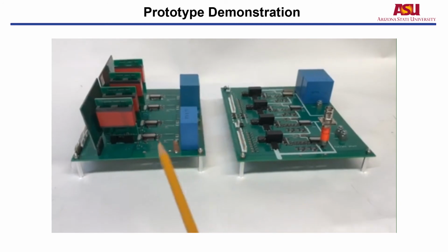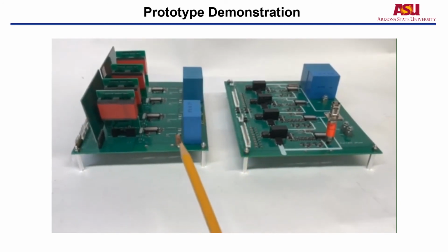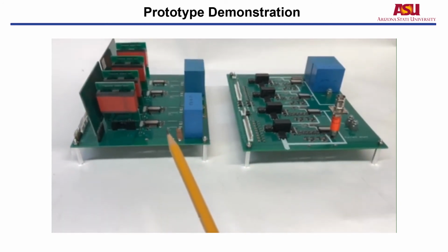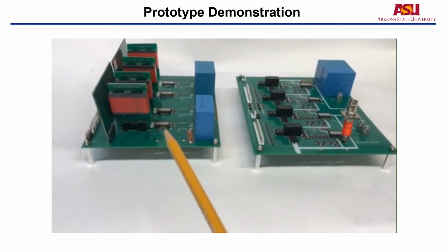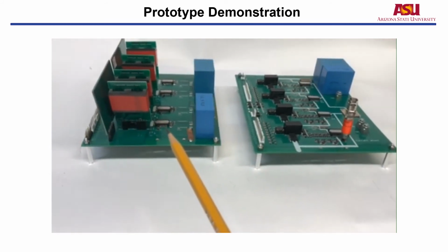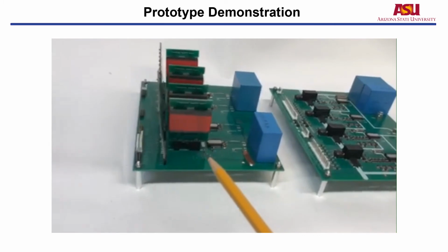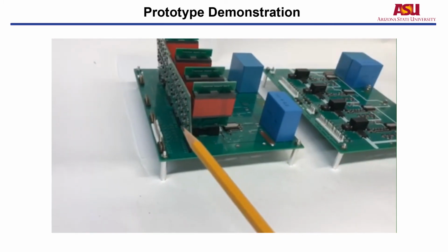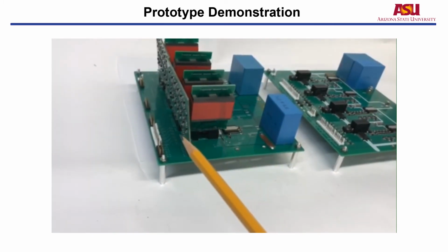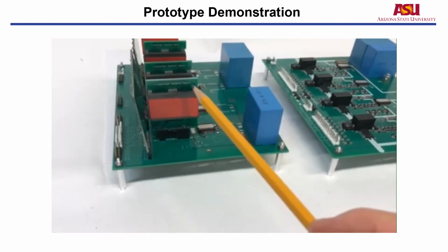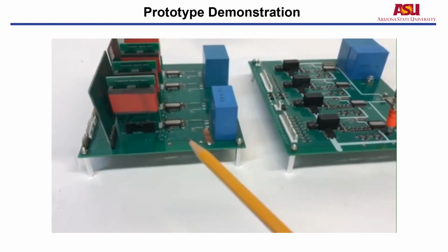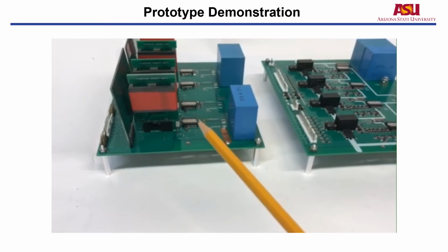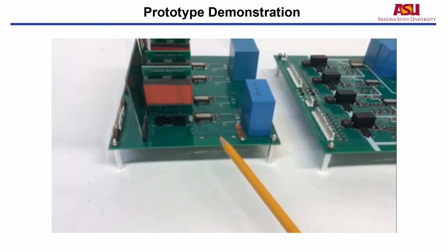These two prototypes are the multiple pulse testers with the series connected GaN devices. For the main devices, we use Infineon GaN devices. So this is prototype 1. The first version has the primary side current mirror daughter board, the isolation transformer, and the secondary side current mirror circuits, which are located on the bottom of this motherboard.